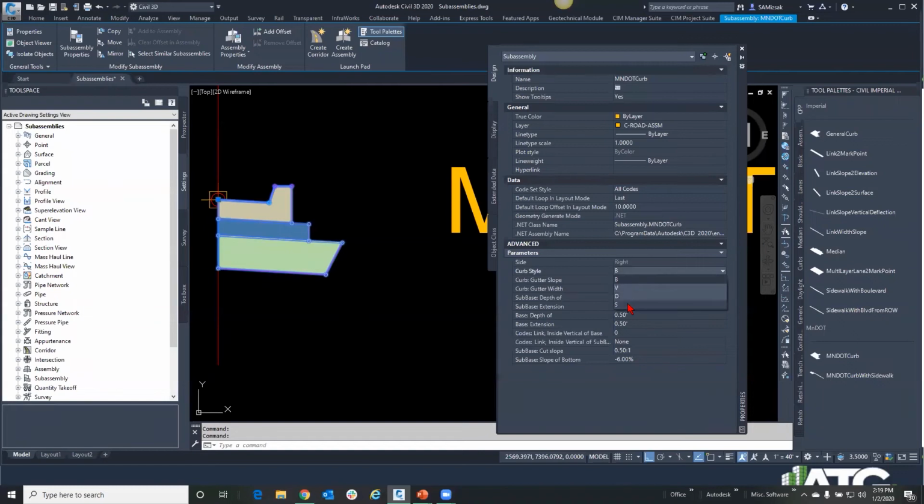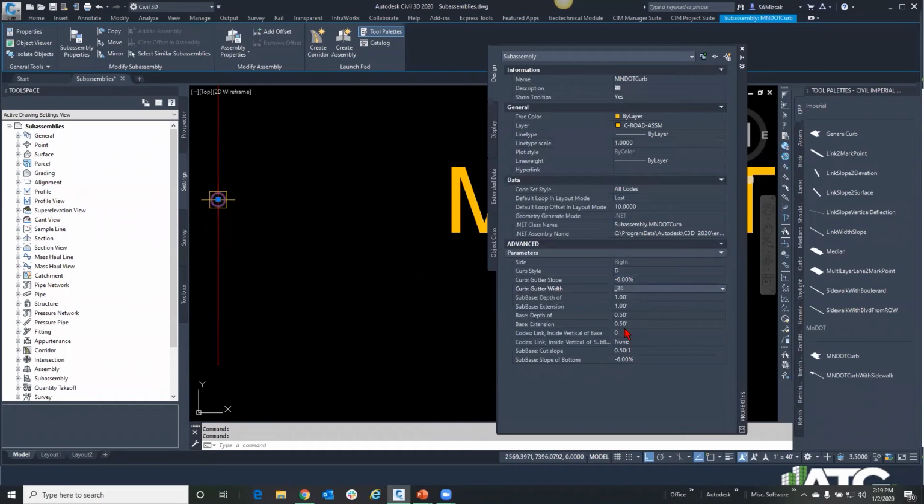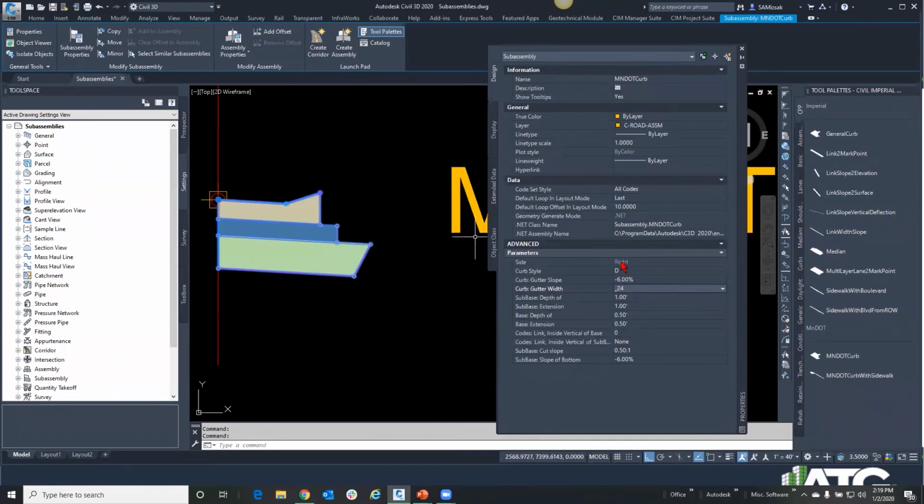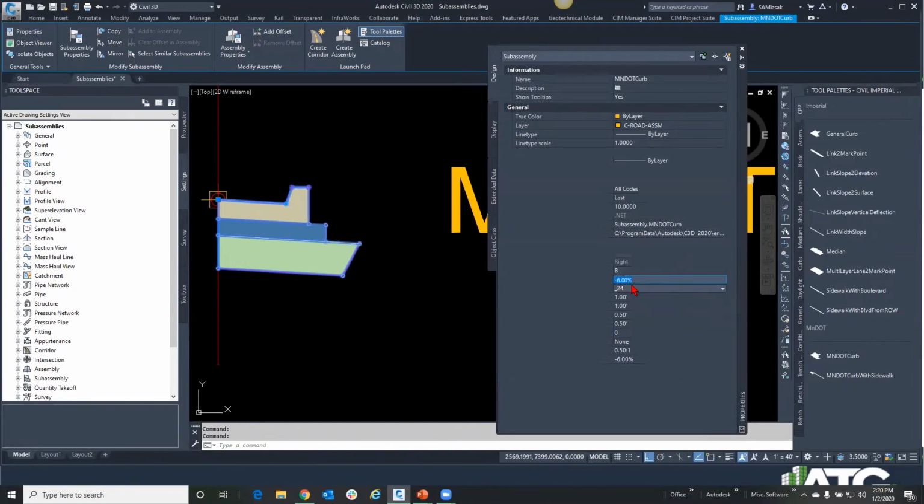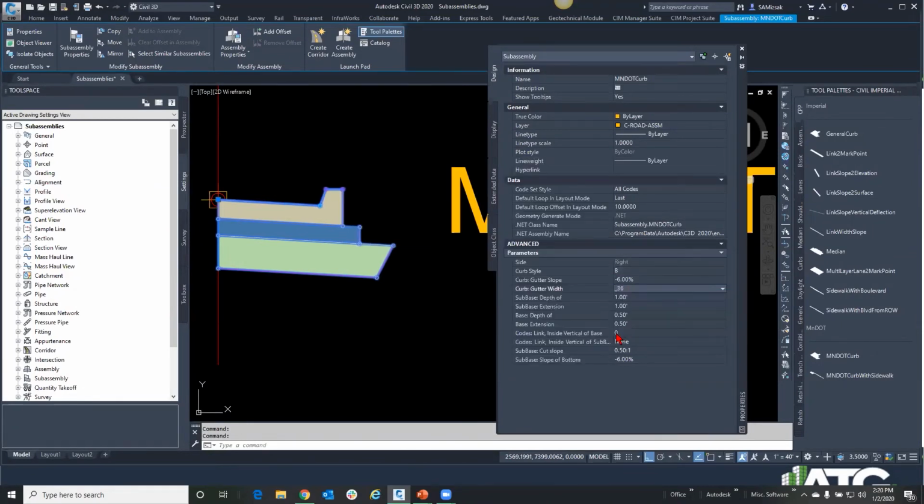If you choose a curb, D36, well, there is no D 36-inch curb. You can't have a D style curb and 36-inch. You can't have it be 30 inches, but it will take 24. So if it makes something that doesn't match the standard template for MnDOT Curb, it just will not build, and it will show you that by not building it. But yes, B 36-inch gives me that.